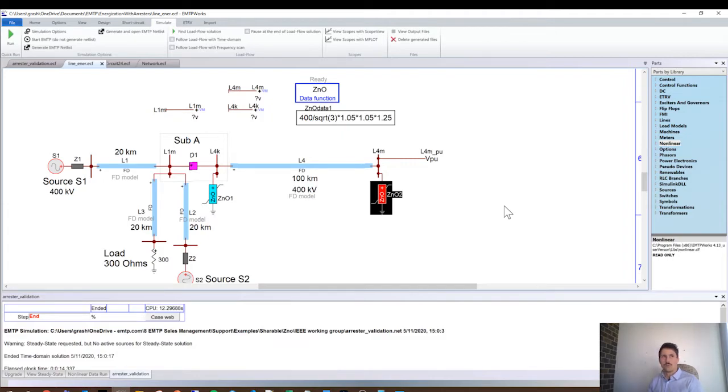And when you do the study to find the maximum voltage you get, you should take basically the curve which for a given voltage level has a lower current. And that will give you the worst case for a switching study. Now if you do energy absorption, it's the opposite. You will take the VI curve where for a certain voltage level you have a higher current, and that will create the maximum energy.